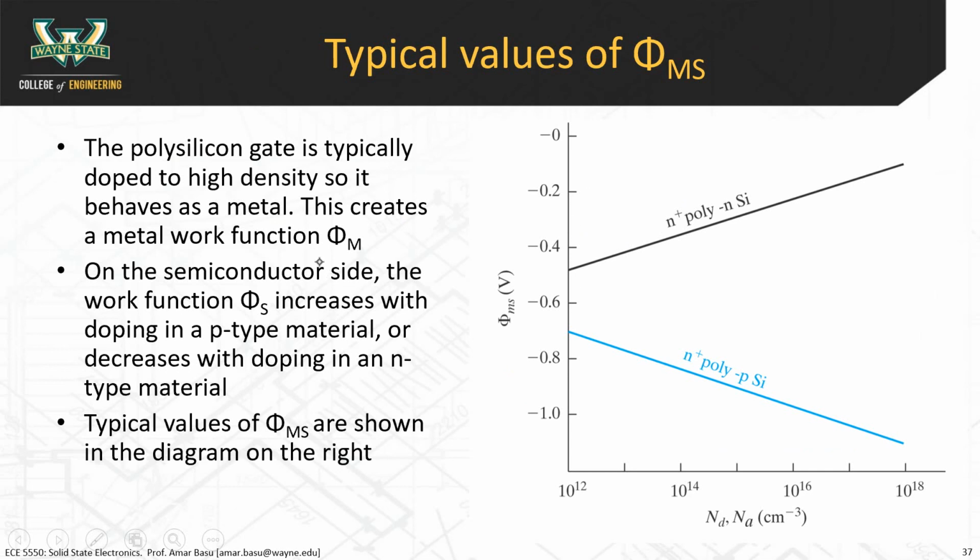have to do with the doping of the polysilicon gate. As many of you know now, there are source and drain regions here, there's a gate oxide material here, and then on top of that, the gate material is polysilicon. Polysilicon has a certain metal work function, and then there's a semiconductor work function in the gate. So this has a phi m associated with it, and then the semiconductor has a semiconductor work function phi s. And so the phi m minus phi s is what you're going to be using to figure out your flat